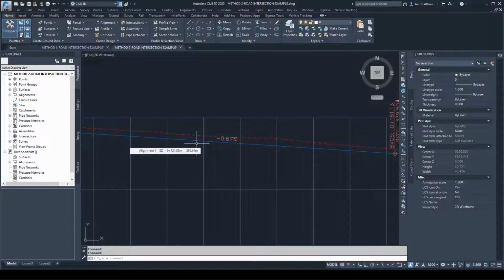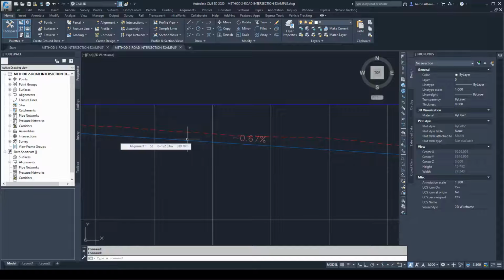As we agreed, the aspects or parameters of design for a rural road are completely different compared to an urban road. If we are looking at a rural road, country road or highway, we have to look mainly into the vertical and horizontal curves, the K value of the vertical curve, and the radii of the horizontal curves. We have to make sure a good ratio between cut and fill is achieved to create efficiency in construction. These are the main criteria for a rural design. For an urban design, we try as much as we can to be as close as possible to the existing ground to minimize the amount of cut and fill.